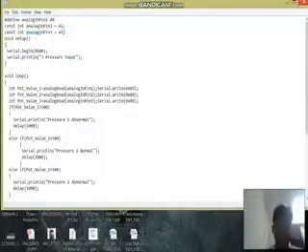Now we will be setting up an input code for all the three pressure sensor inputs. Over here, Serial.begin(9600) and Serial.print for the 3 pressure inputs. Now we will be creating a loop where all three pressure sensors are connected to pin number 1, pin number 2 and pin number 3.